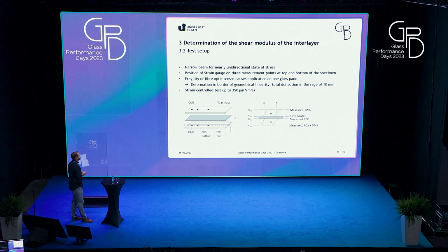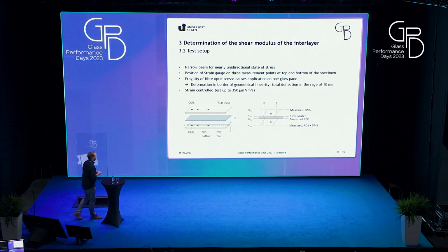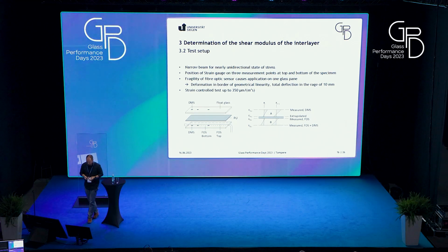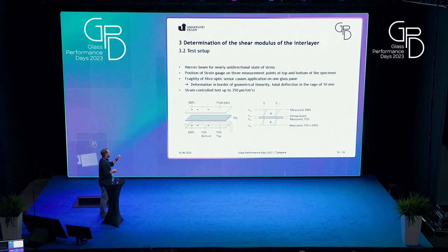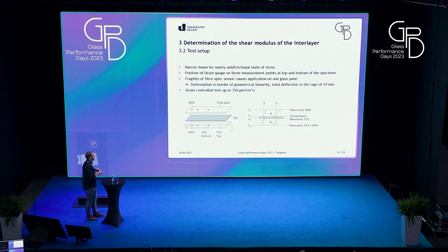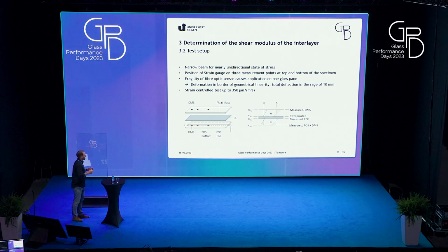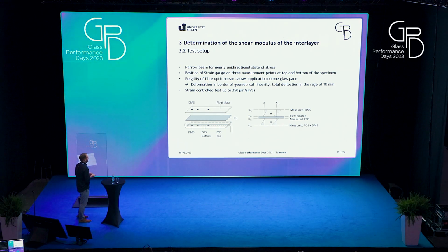So you can say that the deformation is in the range of geometrical linearity. There are no effects that come from any membrane load-bearing effect. So it is possible to extrapolate values that are measured from the bottom glass pane to the top. And we turned the test setup around and repeated the test, and the values are exactly the same.